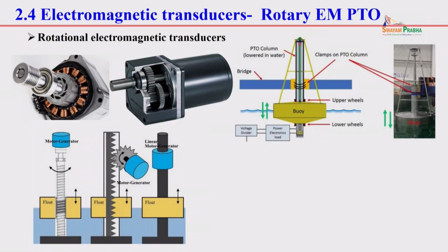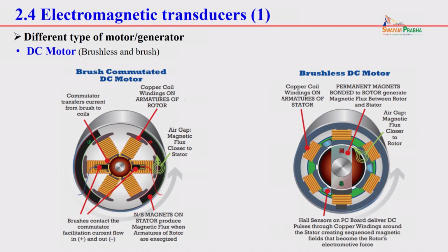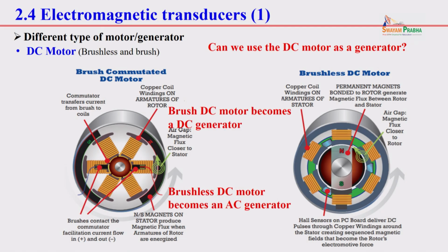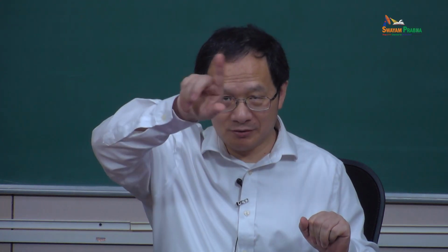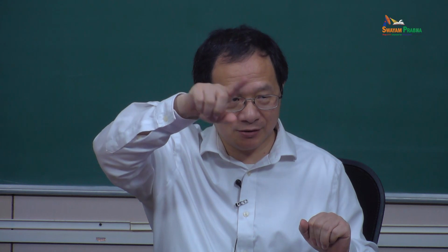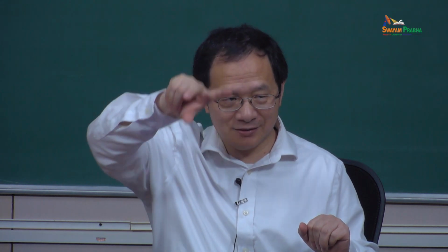However, for a brushless DC motor, when you use it as a generator, it will become an AC generator. You have three phases like that, and you don't use the Hall effect sensor to generate that. Therefore, you rotate this shaft in one direction only, and in turn you get AC voltage. Okay, so I stop here.